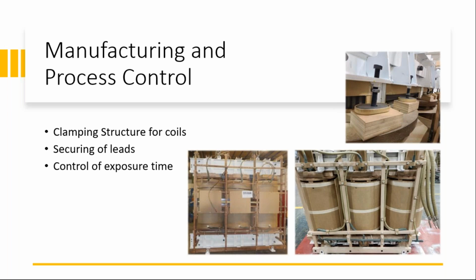At that point, there are additional precautions which need to be taken before the job is tanked. The drying process is very important to achieve 0.5% moisture in power transformers. Also at that time, we measure the actual height of the coils in the clamp condition and ensure it meets the required engineering value, and is close to what we did in the coil sizing process.